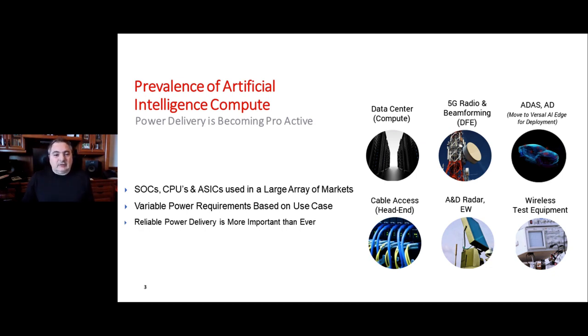So how do we know what that load profile looks like? That's going to have to be a conversation between the system engineer and the person that's writing the Verilog. Maybe they're the same people, maybe it's a huge team. But the point is, different applications on the same chip. So it can't just be boxed into a certain known profile. So we have to think about what that profile is going to look like. And of course, with an FPGA, the fabric can change. You know, these things are field upgradable.